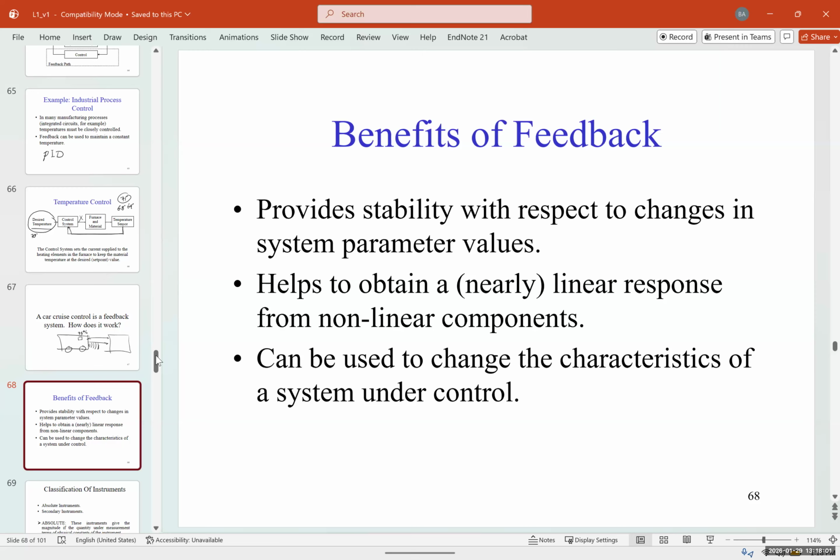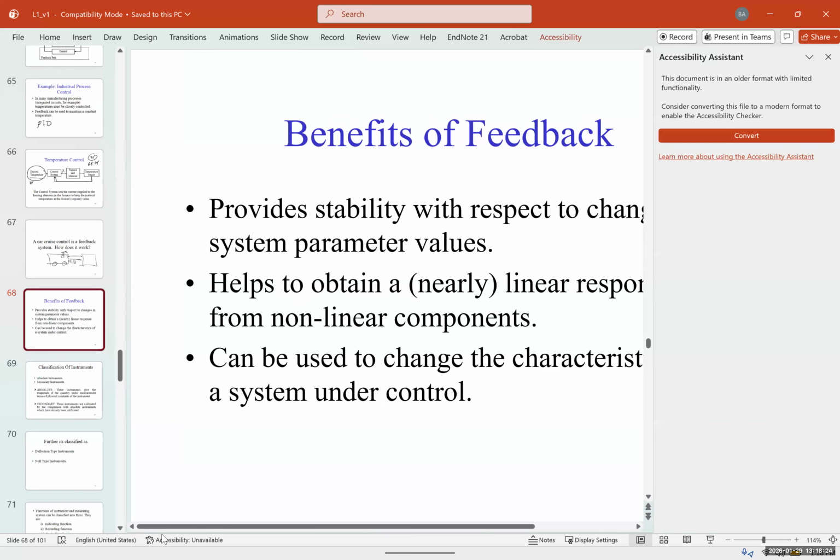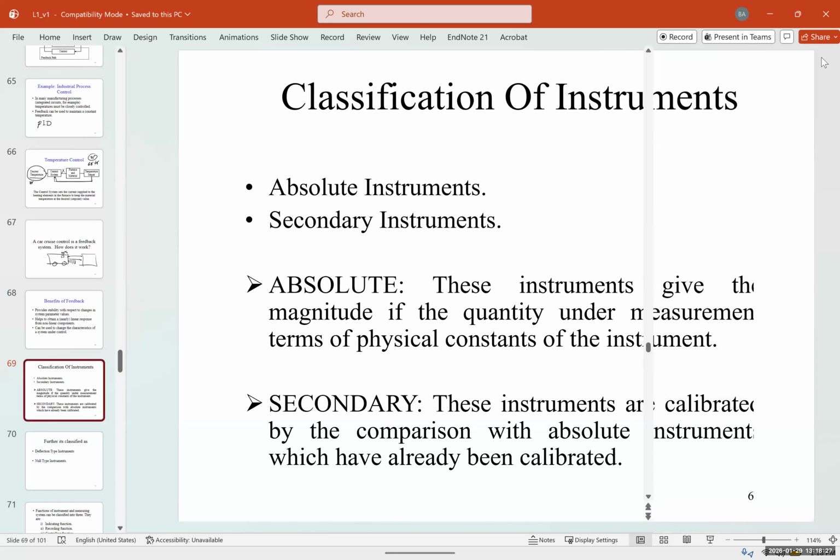The derivative, as you know, calculates the slope, so any small changes are rapidly responded to. The integrator measures the area under a curve, so it's like smoothing and averaging a system. So integration is very good when you have noise, and the differentiator is very good when you want a fast response.